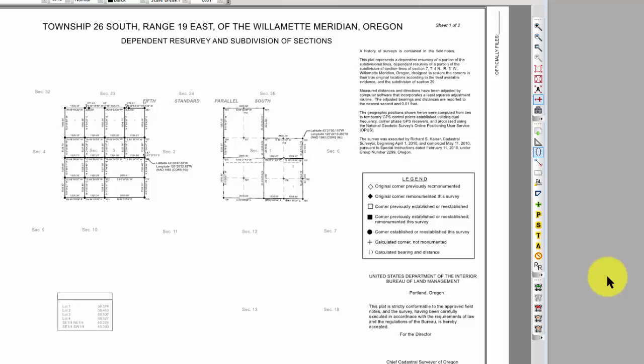And then we've got these latitudinal arcs that we have to follow along where the latitude is constant, but of course on a projected grid the coordinates are going to change. And I'm not going to go through that whole discussion that we did in CRS Part 1. You can go back and watch the video. We laid that all out running a grid line due west as far and compared that with running a true line, geodetic line true due west.